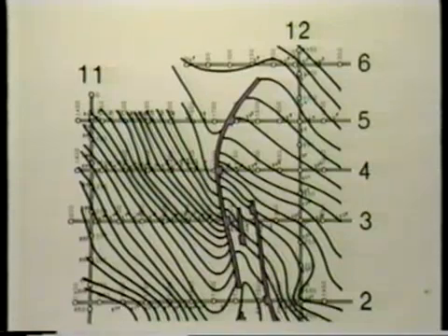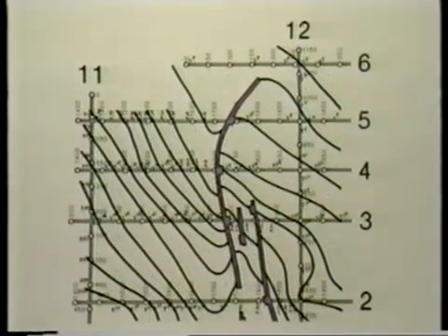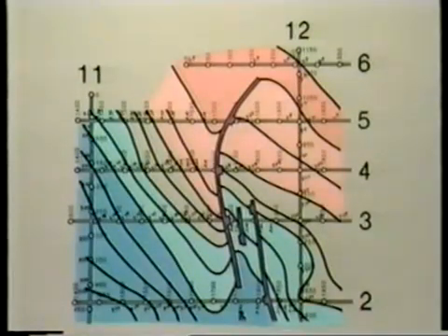After we're sure we have it right, at a fairly detailed contour interval, we can simplify the map by omitting alternate contours. And the message? A north-south anticlinal nose, faulted down on its east flank. Pretty, but a bit fast. Let me just check it.